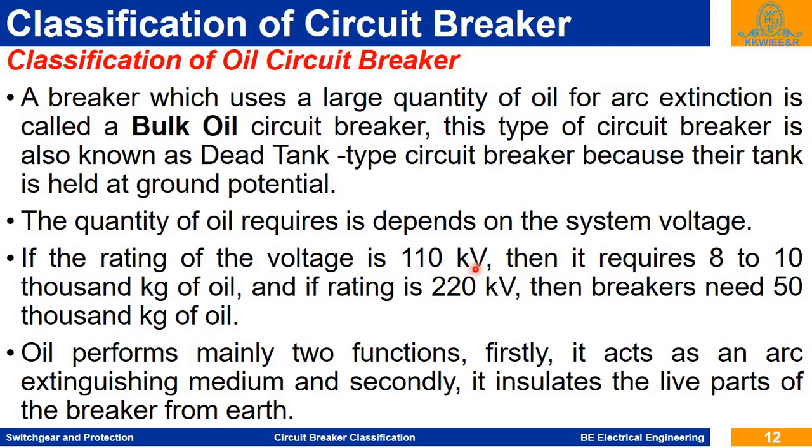For 110 kV, 8 to 10,000 kilograms of oil is required for this circuit breaker, and for 220 kV, it is 50,000 kilograms of oil. From this quantity, you can see why it is called a bulk oil circuit breaker.